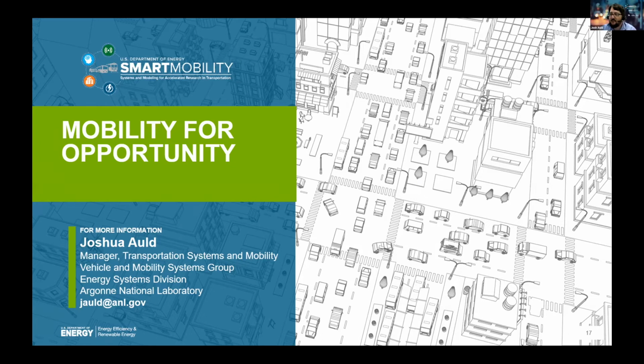I'm assuming, Kara, this is referring to local streets and cul-de-sacs and suburban type streets that are typically missing from these models. It is a fairly significant portion of centerline miles, although much less if you look on a VMT basis. So typically it's less than 10%. We are exploring, and possibly you're aware we're working with some of your team and other teams as well, what impact that has, especially those missing lane miles on shared vehicle type systems. So if we have vehicles running through and picking up people and doing door-to-door service, it becomes more important both on the shared mobility side as well as on the local delivery side, as we do have substantial freight simulation, where moving a couple blocks to drop off and then the Amazon truck moves to the next few blocks.